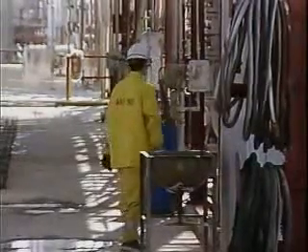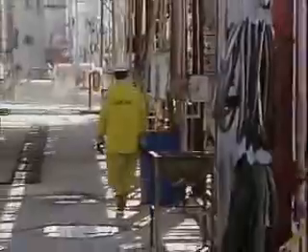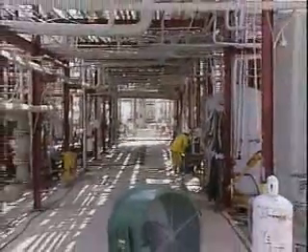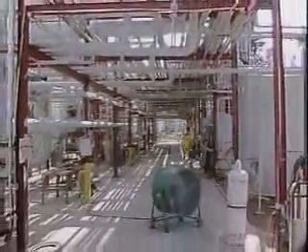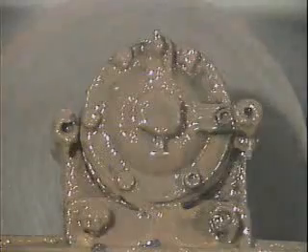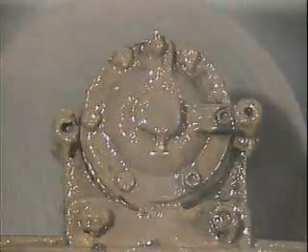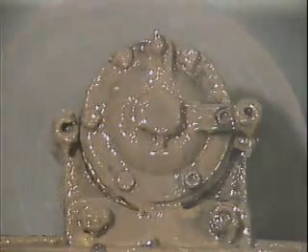Substances or conditions in the environment where a lubricant will be used also affect lubricant performance. For example, a lubricant must be able to withstand chemicals that may tend to break down the lubricant. And if there's water in a system, a lubricant that resists emulsification is usually required.